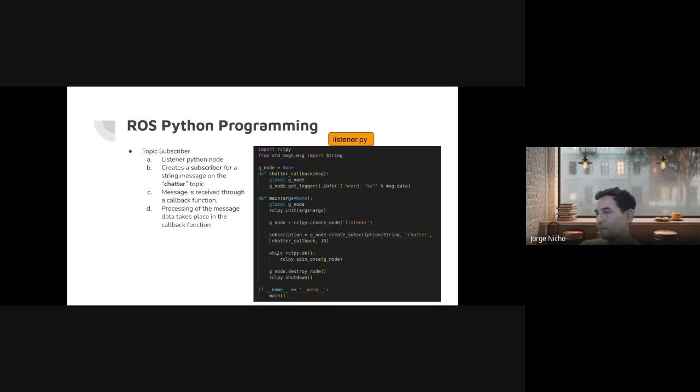So once we do that, then we enter this while loop, which is only checking that ROS is still running. So that .ok is all it's doing: is ROS still running? Yes, and so it'll basically be caught in the while loop, receiving messages. And you have to spin, ROS is just another requirement. When you're receiving messages, there's like a queue of messages that builds up internally. And in order to process those, you have to call this spin method in order to process the queue. And so that way the callbacks get the messages and they get processed.